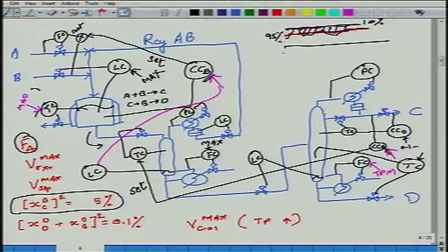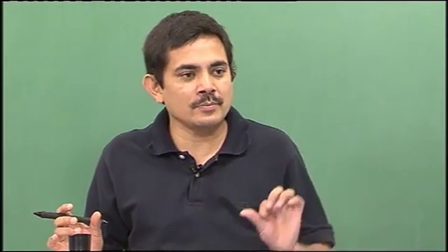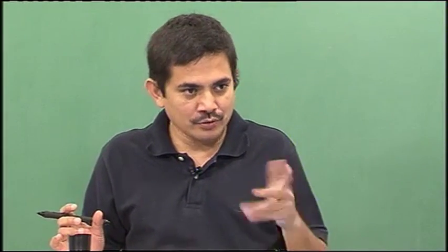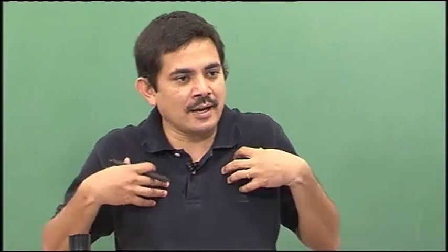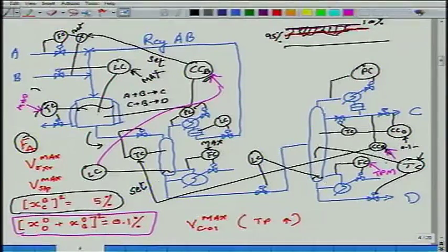If I prevent B from leaking down the bottoms, the point that I am trying to make is XA plus this guy, the last constraint. I could have in my product a large amount of B and very little D, such that they sum to 0.1%. Alternatively, I could have a large amount of D and very little B. I could have both scenarios. The point is, that's in my hands. How is it in my hands? If I set the B set point, the D set point is 0.1 minus that.